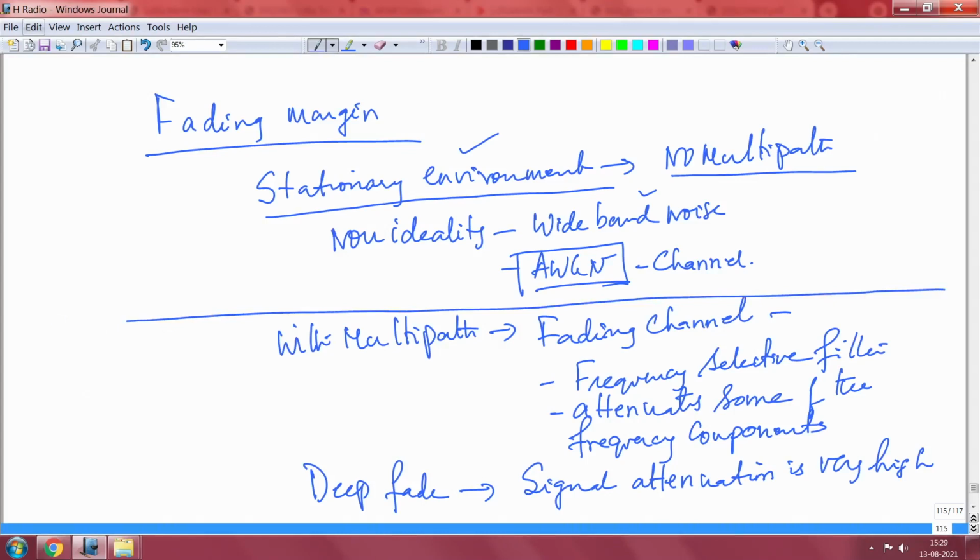Maybe the closest that you can think of, if you want to get to additive white Gaussian noise, is to take the transmitter, connect a cable with suitable connectors and all that, and then directly connect it to a receiver with suitable attenuation. You have to attenuate it because the receiver cannot take RF power directly, it is used to looking at a certain impedance which is matched to the antenna and so on.